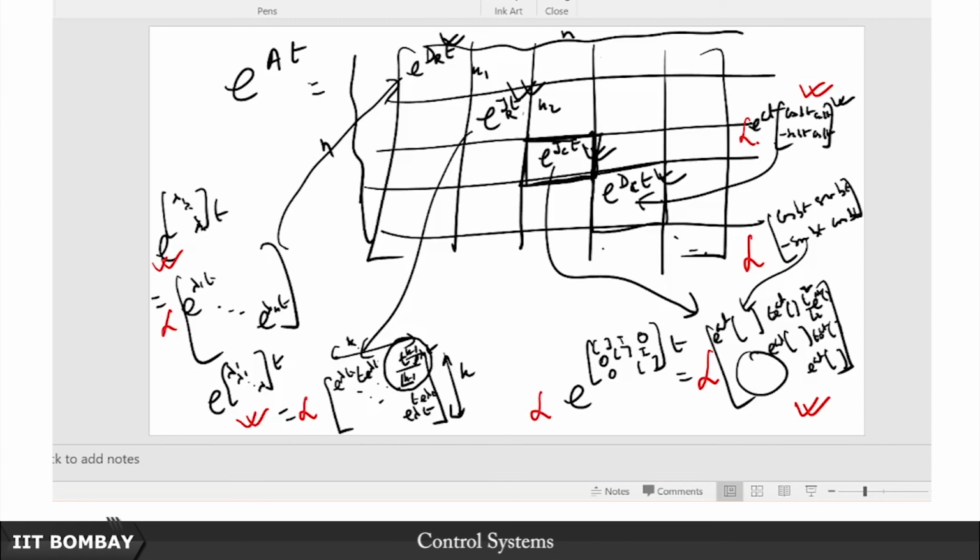If it is the complex conjugate pair, then you again have to have one of the b's and one of the c's, one of the 2 c's or one of the 2 b's for those blocks, better be at least non-zero for them to make an appearance. Otherwise you will be missing out on that second degree factor altogether from the 2 by 2 block, and hence your realization will not be minimal, because your overall transfer function will have a degree which is less than n.